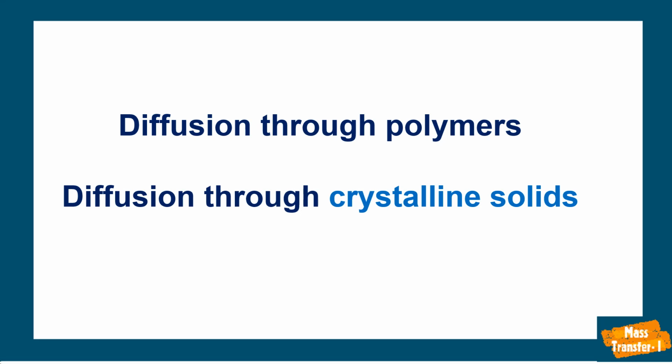Polymers, for example: thin, dense and non-porous polymer membranes have been widely used to separate gas and liquid mixtures in the industries. The mechanism of diffusion is strongly dependent on what type of polymer is being used. It can be crystalline or amorphous, or glassy or rubbery polymer can be used. Commercially, crystalline polymers are about 20% amorphous, and it is mainly through the amorphous region that diffusion takes place. The transport of gaseous species through a polymer membrane is usually characterized by the solution-diffusion mechanism.